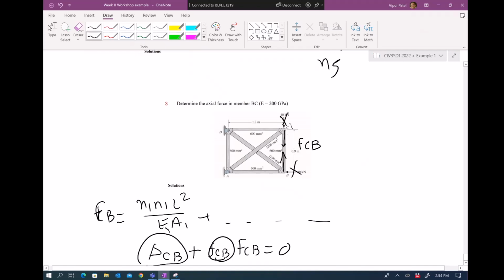Once you found this, you are able to find the unknown axial forces. Right, you understand the overall methods because there are 2 joint methods. There are 2 examples, by the way. The one joint method with the real loads, and then you put the virtual ones, and so on. So you find 2 deflections, make them equal, and that's how you find the unknown axial forces. Right? Any overall questions? I know it's a lot of information, but I just want to give you as much information as possible in 2 hours.